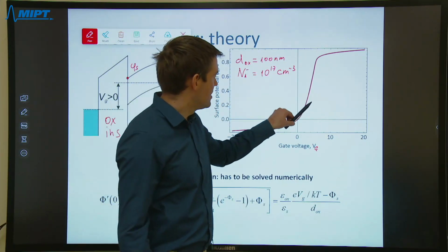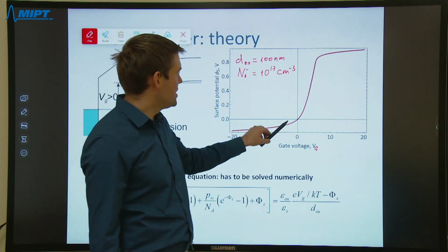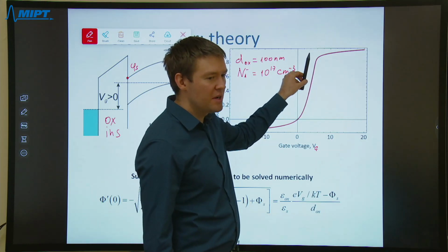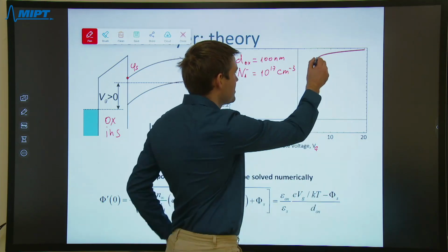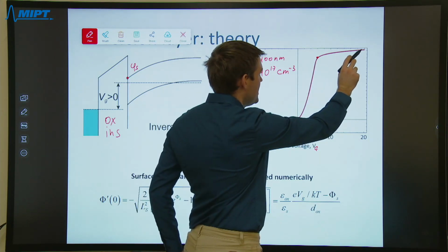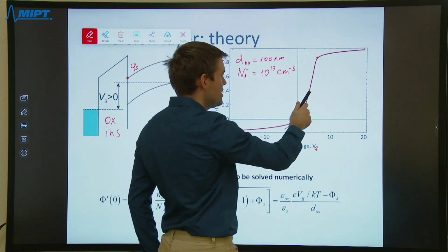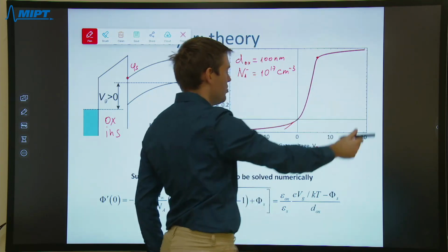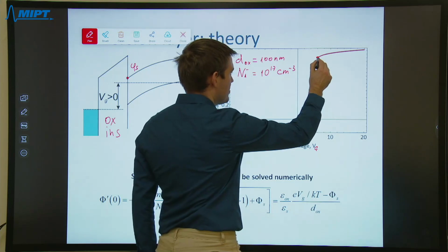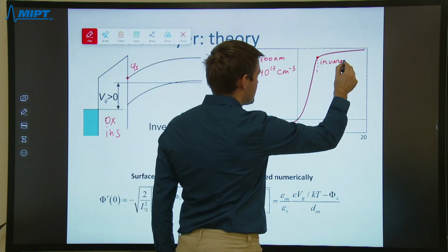Initially it is linear, but it increases rapidly until strong screening by electrons starts. And here something strange happens. Its increase is becoming slower and slower. So initially almost linear rapid growth and then slow growth. Actually, this moment corresponds to the case when the inversion layer starts forming.